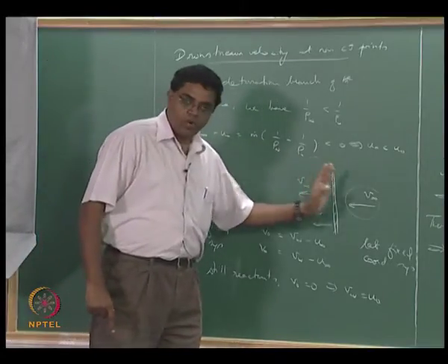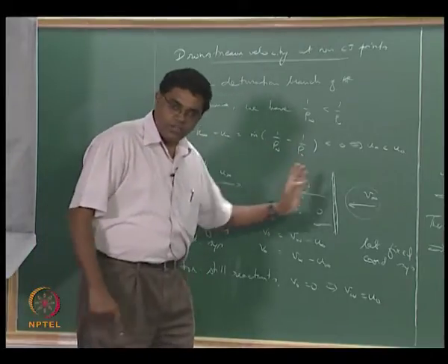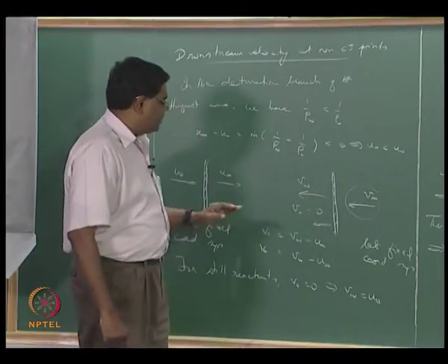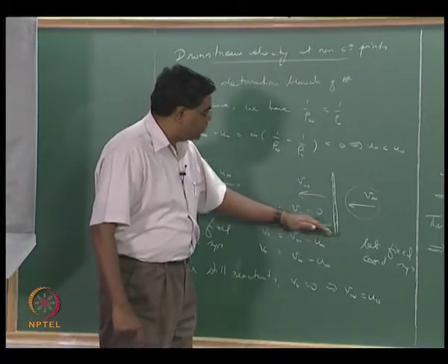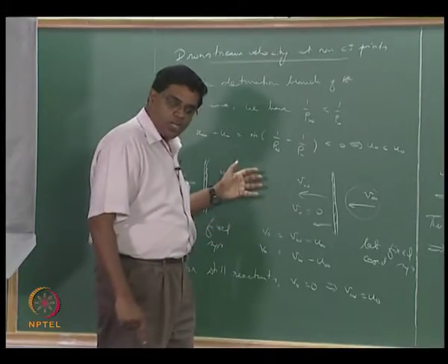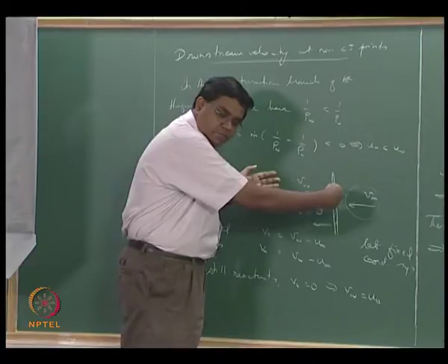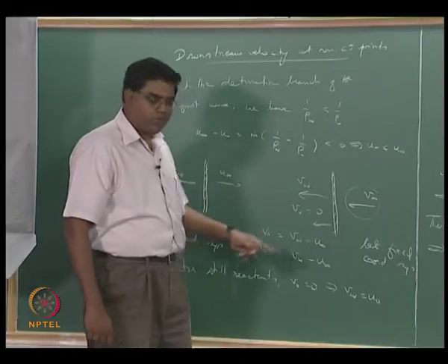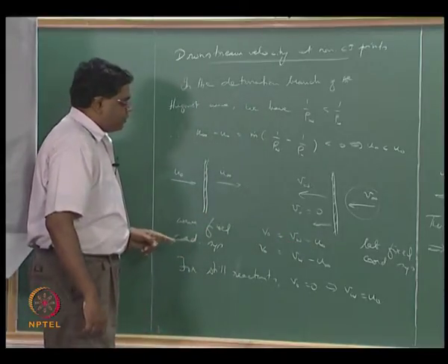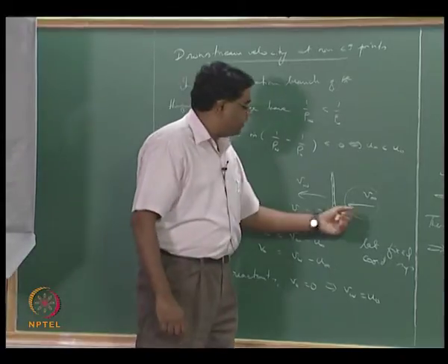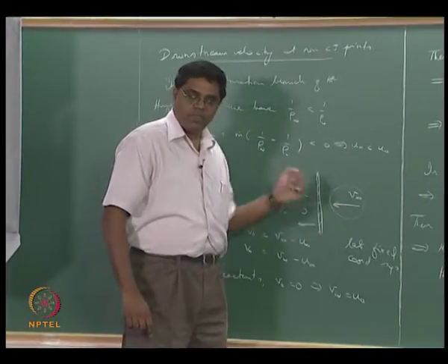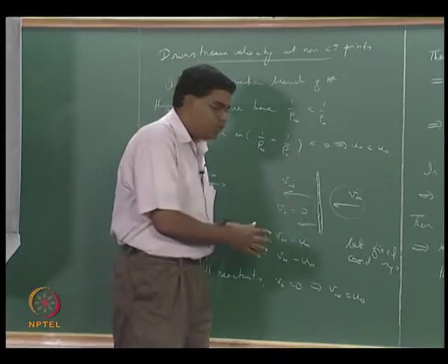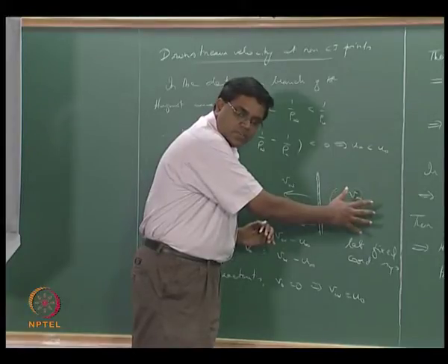When I am in a lab fixed coordinate system, I am just letting the wave propagate into primarily still reactants, but it does not have to be still, okay. But if I am counting for a flow direction, I would count it like this. If the flow were actually approaching the wave like this in a lab fixed coordinate system, I would have to reckon V0 to be negative in the way I am doing this. What you are telling me is, once I find out what my actual V infinity is, is it possible for me to look at that velocity relative to the wave? That means we are now trying to make this still, if that's what I understand.